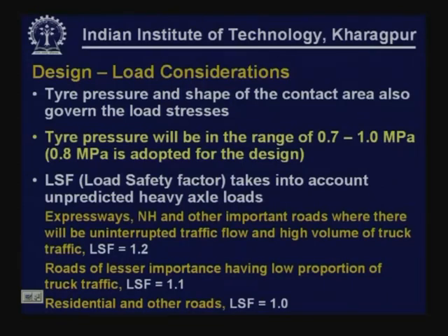For expressways, this brings in an additional safety factor into the design. For expressways, national highways and other important roads where there will be uninterrupted traffic flow and high volume of truck traffic, we are going to use a slightly higher safety factor, LSF of 1.2. Roads of lesser importance having low proportion of truck traffic, LSF of 1.1 will be used. For residential and other roads, no additional safety, so LSF of 1.0 is used.